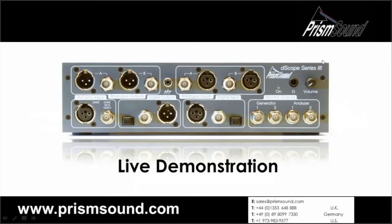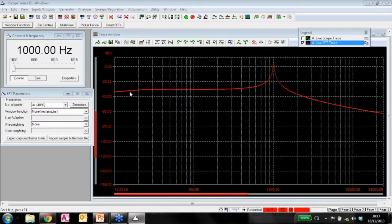Okay, so I'd just like to give you guys a practical demonstration of this now with my D-scope. What I've got on screen at the minute, up the top left here, is a slider which is changing the frequency of my input signal. I've got a couple of options underneath to choose my FFT parameters, number of points and which window function we're using, and then obviously the main majority of the screen is taken up by our FFT display itself.